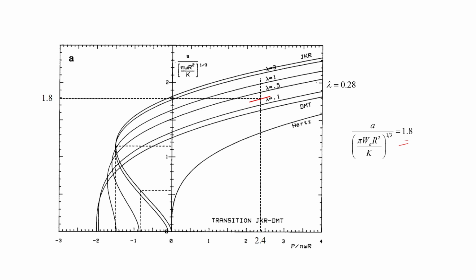So, which is good. So, now we have this dimensionless radius of contact, A. So, A can be found out as 1.8 into, let us say, pi into 100 millijoule, and this is 2 micron, 10 to the power minus 6, squared, and capital K was 0.159 GPa, 10 to the power 9, and to the power 1 upon 3, that is the way.